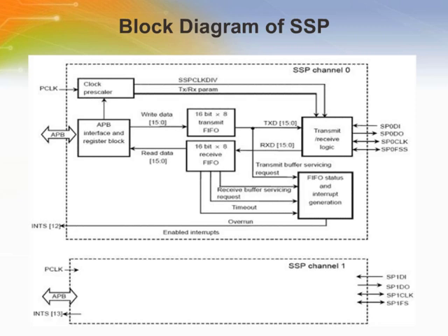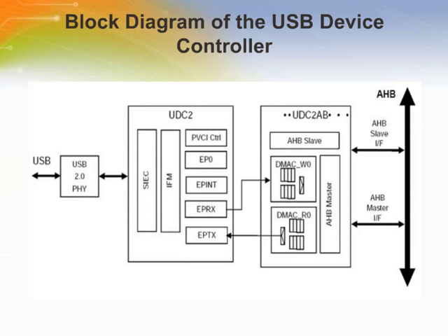USB protocol processing, detects SOF and USB reset, suspend, resume, generates and checks packet IDs, generates and checks data synchronization bits, data 0, data 1, data 2, and M data, checks CRC5, generates and checks CRC16, supports ping, and supports 4 transfer modes: control, interrupt, bulk, and isochronous.